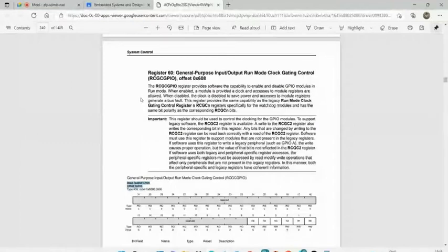Why would you unnecessarily keep the ports at high or low voltage? Keep them off unless you require them to work. If they are not being utilized for any external work or interfacing with the external world, why keep giving power to that particular port?